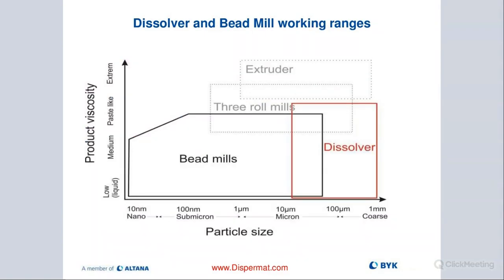So this slide is actually interesting because it kind of shows you the breakout. So we start with the dissolver, and then at about 10 microns, we start medium milling. And so there's different types of medium mills. Some of you are probably familiar with old school 3-roll mills. It's kind of like older technology that's being replaced now with more efficient milling systems, like the basket mills are fantastic. We prove that out in our lab on a weekly basis where we have customers come in.